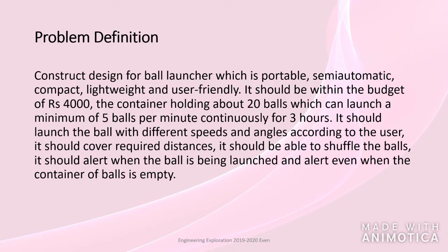The problem or need statement is defined as: construct a design for a ball launcher which is portable, semi-automatic, compact, lightweight and user-friendly. It should be within the budget of rupees 4000. The container should hold about 20 balls, and it should launch a minimum of 5 balls per minute continuously for 3 hours.